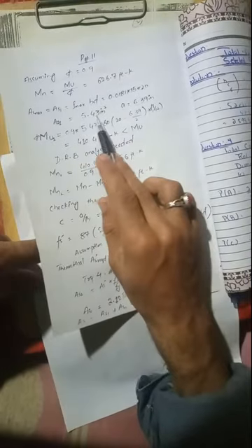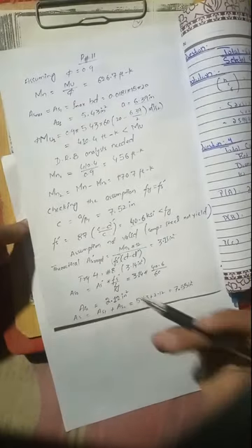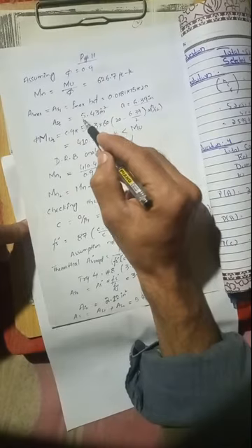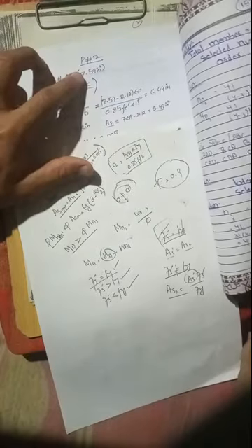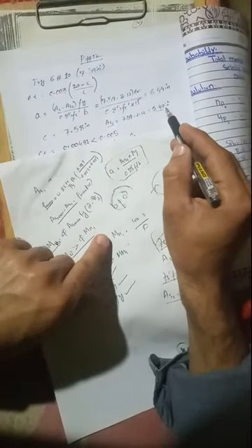Now see, here you see S1 is 5.43, but due to the improper bar selection, because practically you can't choose such bars which exactly give you this amount of steel, alright? So that's why it will change the value of S1, because we choose 6 number 10 bars which give us 7.59. Theoretically we needed 7.55. So that's why we are increasing the reinforcement. Due to this increase, it will affect the S1 value, right? So the exact value of S1 is 5.47.